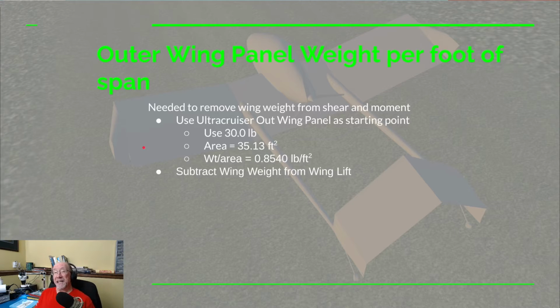But in order to subtract that out, we need to have a guess at what that wing weight is going to be. And we haven't done that yet. Now there is another airplane out there that is all aluminum, what we can use as our first guess. And that's good enough for now because this is going to be an iterative process. Because once we get results from this iteration of our design, we can actually do some detailed design on the structure of the spar and then do more accurate estimations of what our spar weight's going to be and the wing skin weight, our aileron weight, our flaps weight, and then do another iteration. And we can close in on the actual real values that we're going to need.